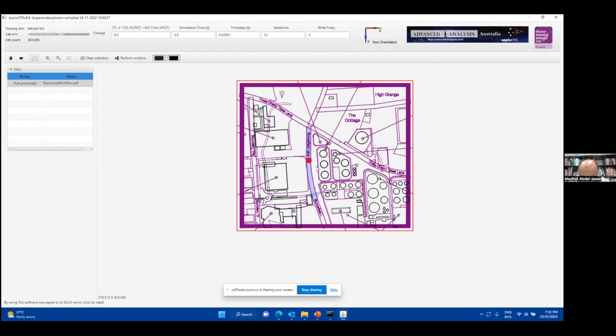I've also, you can see here, I've put the gas cloud across Buncefield Lane, only Buncefield Lane. I'm going to put the appropriate congestion in there so that we're able to run the simulation. By the way, to put in the gas cloud, you could just right click and go custom cloud and select the gas cloud, and just make sure, this is important, make sure you press escape once after you've done the gas cloud selection.